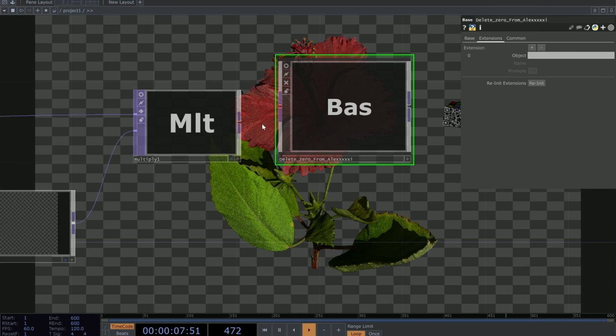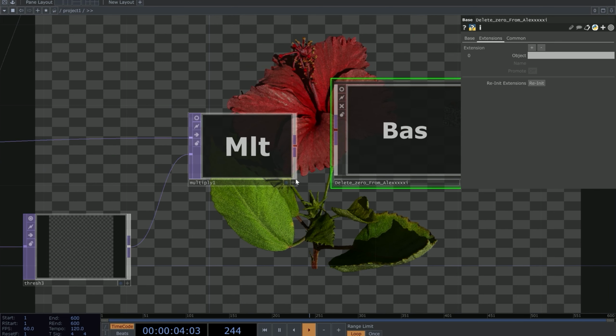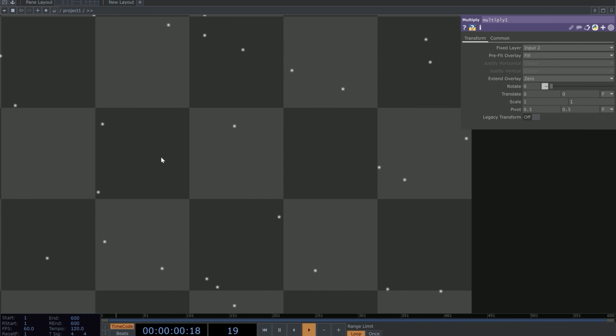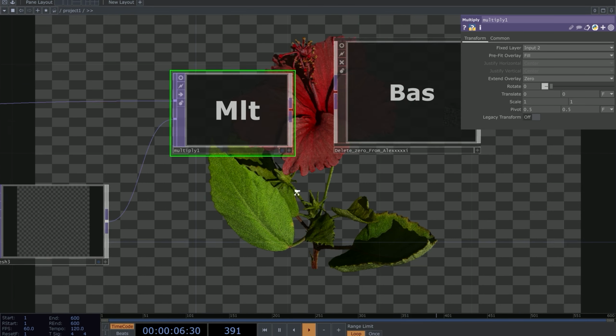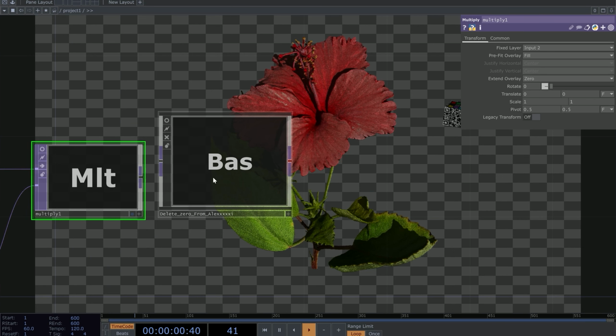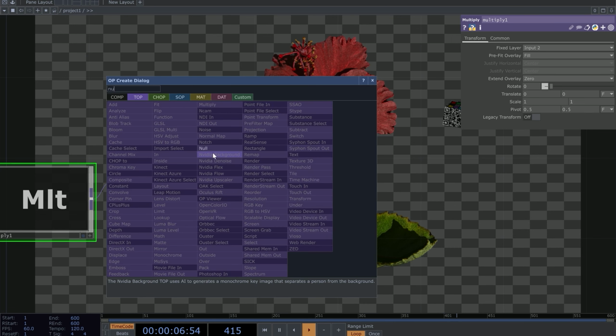And we don't need these transparency points, right? In the back, if we want to render all these points, it would consume a lot of our computer's performance. What we actually need to render is just this small part of the cross-section. And for the other parts, we can see these transparent areas, which is actually a point that overlaps at the world origin of 0, 0, 0. So we need to use this delete 0 plugin, which I made myself, to delete all the other parts. Then we connect it and then we create a null.